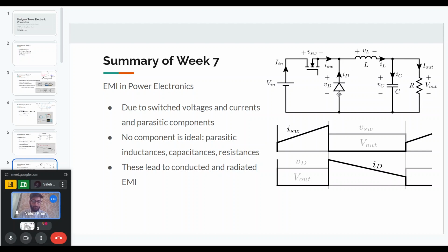Similarly, because every current-carrying conductor produces a magnetic field, it will act as a very small inductor. Even though this is not done intentionally, we don't want a simple wire to behave as an inductor, but it will have some inductance because of the inherent nature of these devices. And so these are called parasitics.